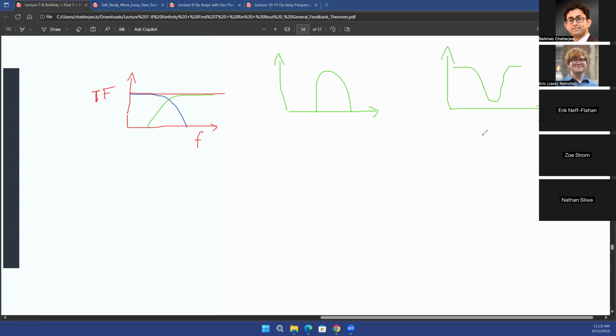So you have some idea about high pass filter, low pass filter, band pass filters, band stop filters, and so on. And as you know, you're only interested in those filters because they are dependent on frequency. So if you want to filter out a certain frequency range, you'll go for a band pass filter. You want to get rid of, let's say, the 60 hertz noise coming from the power lines, you generally go for a band stop or a notch filter at 60 hertz so that your circuits are not affected or impacted by the power line interference. You may have a high pass filter or a low pass filter depending on the need of the circuit.